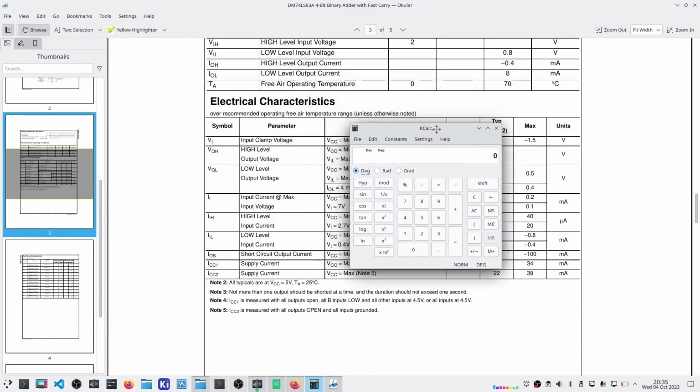Now if I do the math on that, 1.5 divided by 0.0008, 0.8 milliamps, I need something smaller than an 1800 or 1900 or 2000 ohm resistor to overcome that. Is that what I'm reading? Certainly a 10,000 ohm resistor isn't overcoming that.